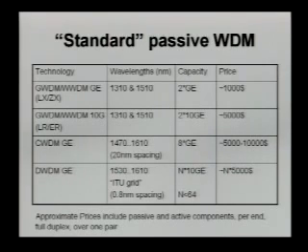These are the standard technologies you could use for WDM. First, you can do wide wavelength division multiplexing. Basically, you have LX and ZX optics and two wavelengths. That gives you 2 gigabit of capacity. You can do the same thing with 10 gigabit Ethernet using LR and ER optics, and you get two 10 gigabit Ethernets.